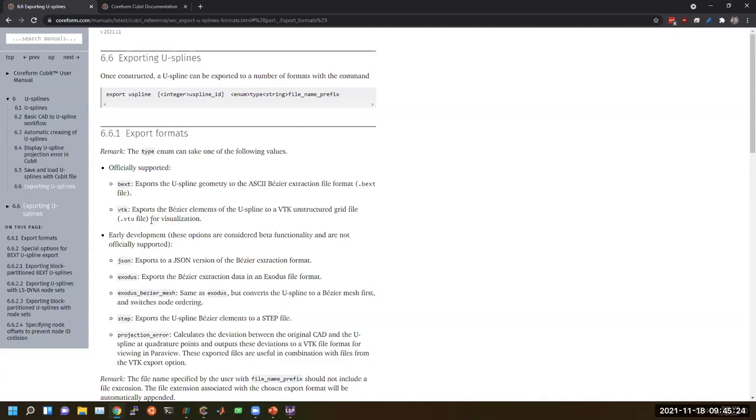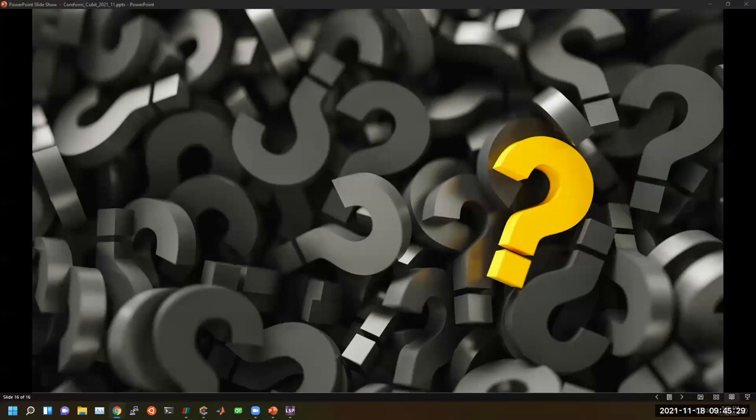Okay. Question from Ben: does Coreform IGA support dynamic simulations like vibration analysis, linear wave propagation? Yeah, so we fully intend for Qubit to be a fully featured linear and nonlinear solver for both solid mechanics as well as heat transfer, coupled mechanics. And so included in there are dynamics. We don't yet have an eigenvalue solver that's accessible to users, but our linear solvers right now are based in PETSc, and so there are some eigenvalue solvers in there. But we do support explicit dynamics already as well. So right now we've got implicit dynamics, explicit dynamics, and then we're working on these other kinds of solvers. But if you have specific techniques you're looking for, we'd love to hear which techniques are important for you.